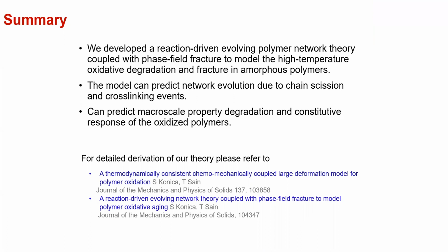Yeah, that is actually the first sign of oxidation, when a material loses its glazing, like you said, going from white to yellow. That is one way to say the material started oxidizing, but it could be another kind of degradation too, like moisture absorption, oxidation plus moisture, or photochemical radiation. In most cases, when we see lights going yellow, it's probably the covers of the lights turning yellow, a photo radical reaction. There are a lot of teeny tiny degradation mechanisms in polymers that all come into the picture, so it's hard to tell which one is actually turning them yellow. Okay, thank you.